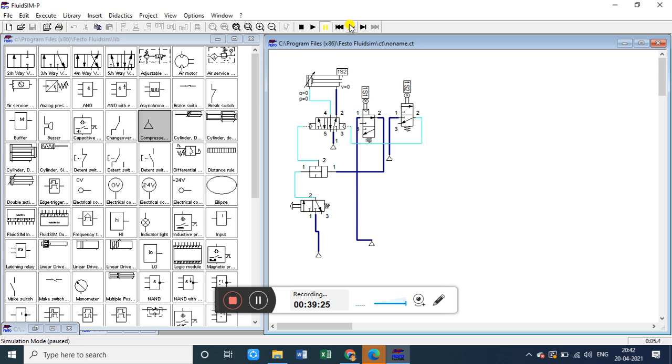So now by clicking so many times on this single step, you won't get any output, because here the cycle will end. So I think you have understood the working of this system that is designed for controlling the double acting cylinder by using this 1:1 and 1:2, that is two limit switches, and this 3/2 valve with push button, and this AND valve. This is a double-sided 5/2 valve. This is a double acting cylinder.